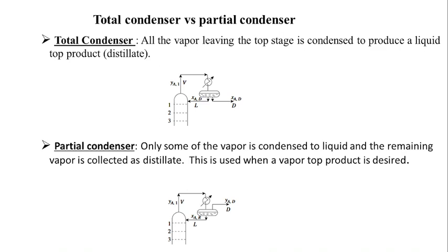The liquid falls from the downcomer above to the tray, flows over the tray, goes to the downcomer by crossing over the weir, the outlet weir, and falls to the next tray. It is possible for you to have a larger downcomer width. Yes, true. But if you do that, the space which you shall be allocating for your vapor dispersers will become less.